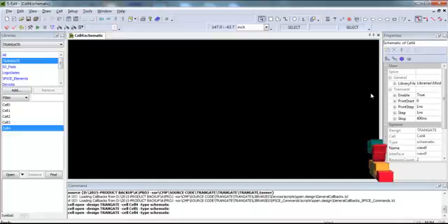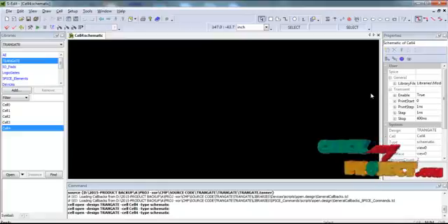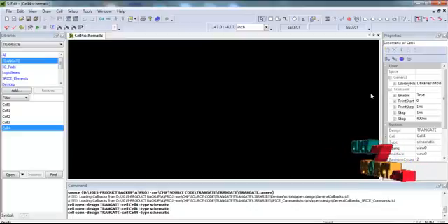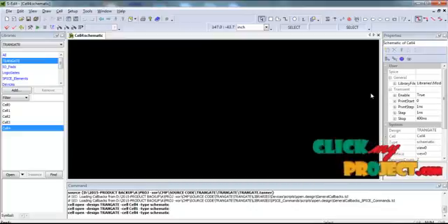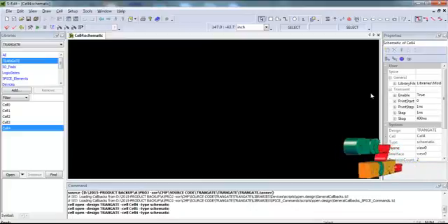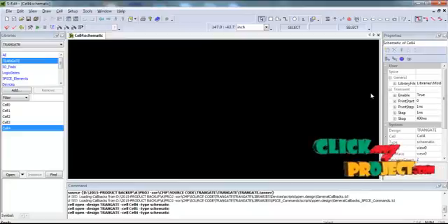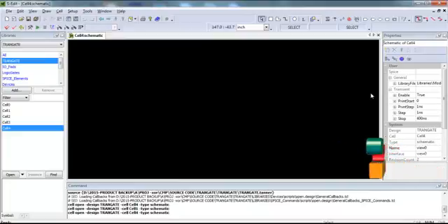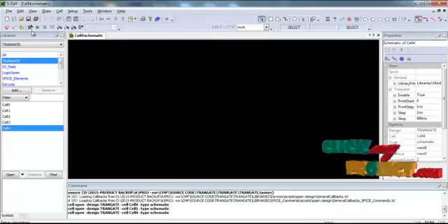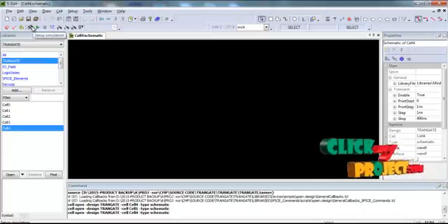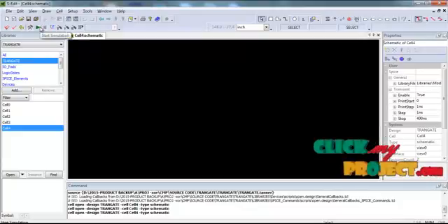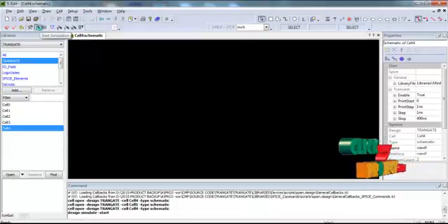We implement the CMOS circuit based work to produce the voltage output variations and to calculate the power and delay time variation for the overall 8-bit adder circuit, and compare with the previous power consumption. This CMOS design improves the adder performance level in the physical oriented diagrammatic representations. We run the symbol, then run the output and set up the simulation to set the time period and time step. Then you just run the start simulation to get the final output.